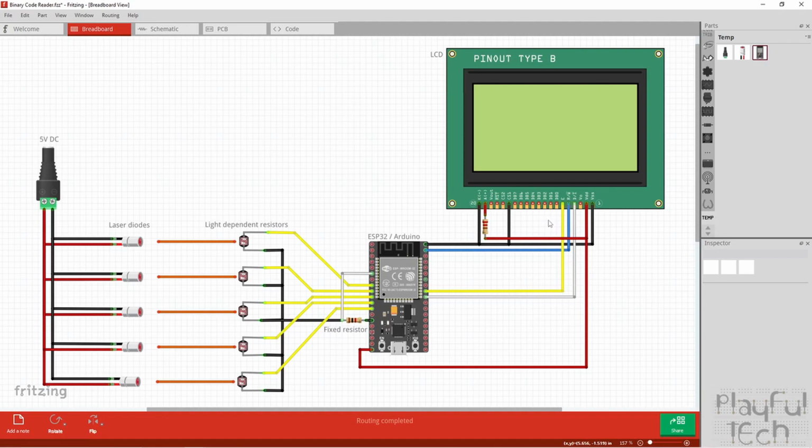The only other thing we need to do is to power it. So even though an ESP32 runs at 3.3 volt logic, the LCD display requires 5 volts to actually energize the crystals in the display. So we connect VDD to the 5 volt output pin here. We connect the grounds together. The SPI interfaces, by the way, don't need to have a logic level converter. Even though the power for the crystals is running at 5 volt, 3.3 volt logic works on the SPI interface fine without any need to step it up to 5 volts.